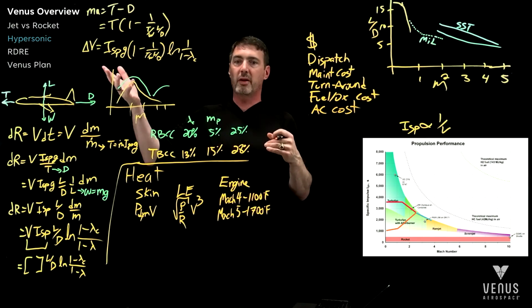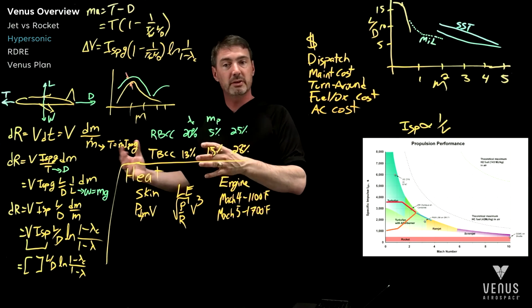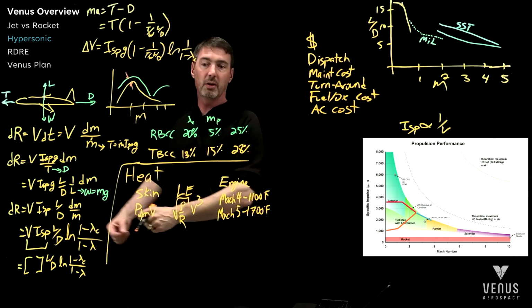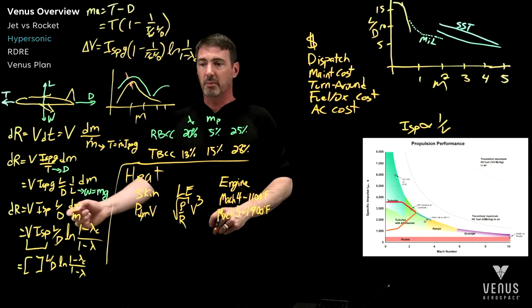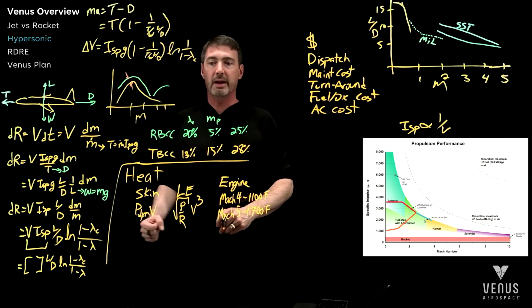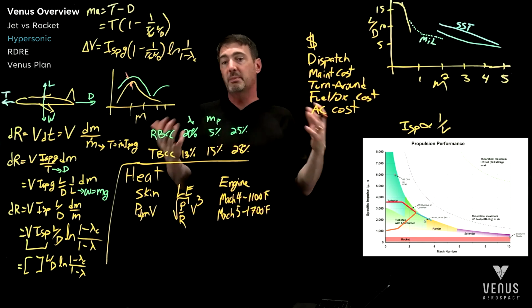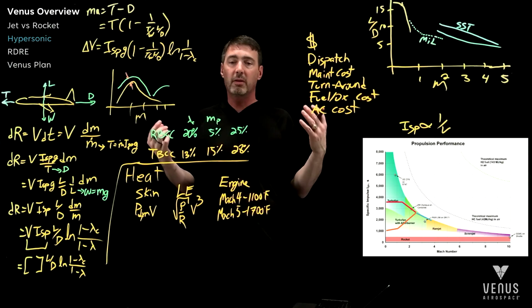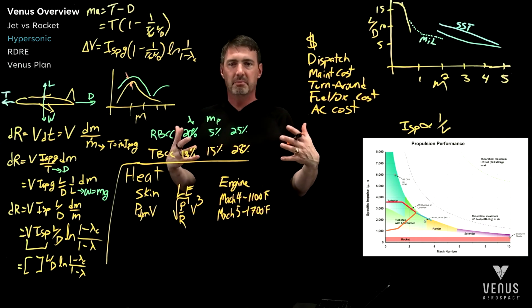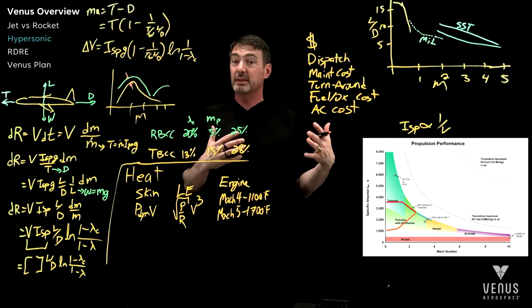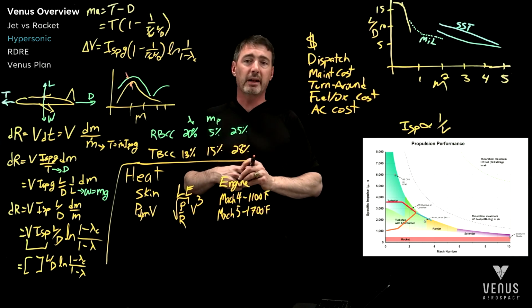So when we're looking at hypersonic, there are some physics challenges. How far are you trying to go? Can you get that far based on your performance, your lift-drag, and how much you're actually able to pack into the vehicle? I mentioned rockets pack 90% propellant into a vehicle. You can't do that at an aircraft level. 50% is very doable. 70% starts becoming heroic at an aircraft level.